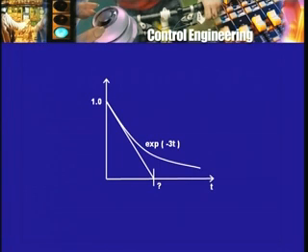So look at this function, think of it as, say, y of t or x of t equal to e raised to minus 3t. Look at its derivative, which gives you the slope of the tangent. Then write down some appropriate equations and verify that at 1/3 of a second, if the unit of time t is in seconds, this tangent would intersect the t axis. This is one interpretation of the time constant. That is, if the initial rate of decrease had remained constant, the function would be 0 at the end of the time duration equal to the time constant, in this case 1/3 of a second.